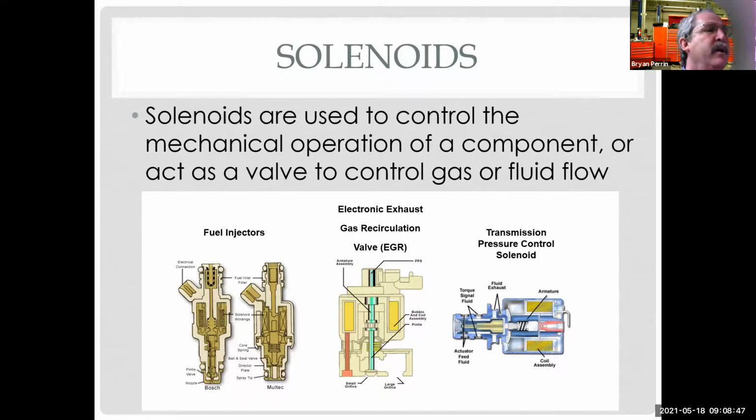So here I have different types of solenoids doing different physical things. We even control them differently electrically. We use all 4 different types of electrical control on solenoids. But they're doing different things. But is really testing them any different? It's a solenoid. Got a power, got a ground. Does it go click when it gets power and ground? It should, because we know that that metal thing's supposed to move inside.